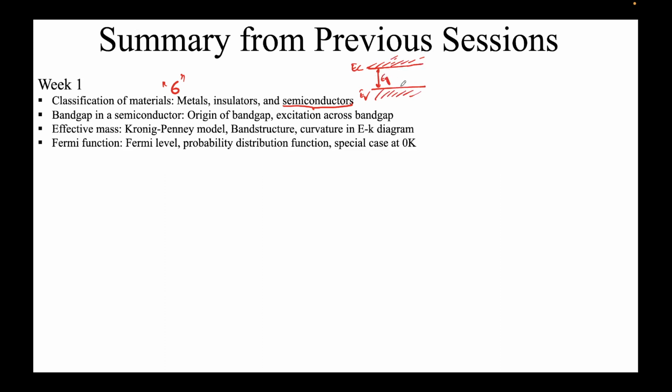And what can happen is that an electron can jump from the valence band to the conduction band or vice versa. When jumping from the conduction to the valence band, a photon can be emitted, which was the principle for the LEDs, as we saw in a couple of problems. Then what we saw is that this is in energy versus space, E versus X. If I draw another nomenclature, E versus K, this is called the band structure. E versus X is the band diagram, E versus K is the band structure.